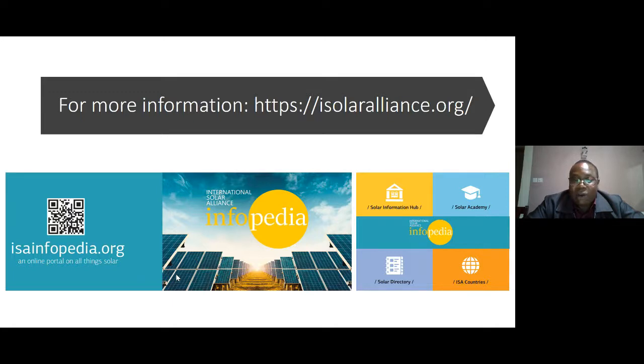Otherwise, for grid tied systems, you have to go to a higher specification, depending on other factors from the utility. They might have specific conditions that you have to fulfill when you are agreeing on how to feed in your power. So the charge controller and inverters really vary on the site, because these are renewable energy systems, and the application is site specific.